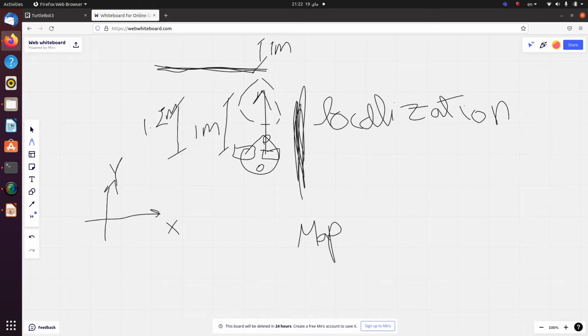Because as we said before, any process that includes integration is called odometry or dead reckoning. And integrating the reading of the IMU is one of these dead reckoning methods. So we've got the reading of the IMU, which says, for example, that you moved 1.2 meters.